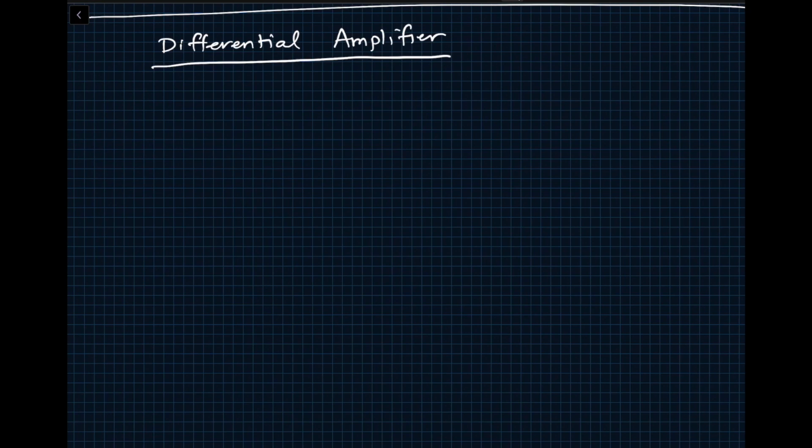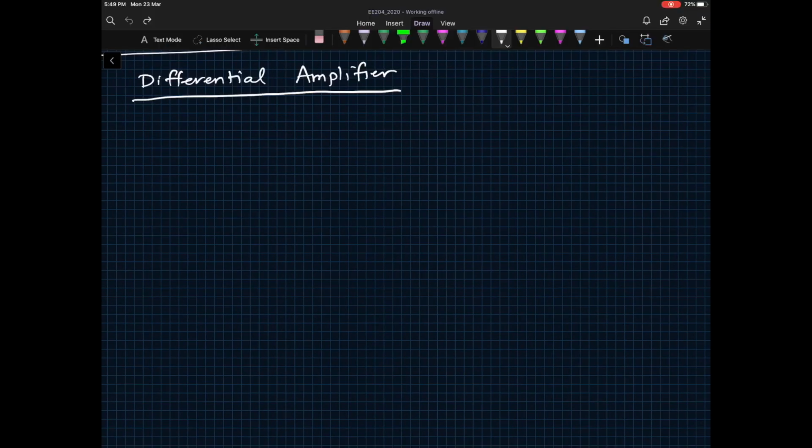Okay, so let's say there is a terminal P and terminal N. What you would really like is that the difference between the two terminals, P and N, we would like to amplify by a large value. However, anything that exists on terminals P and N together, common to both those terminals, VP and VN, like a large hum, we would like to subtract it out.